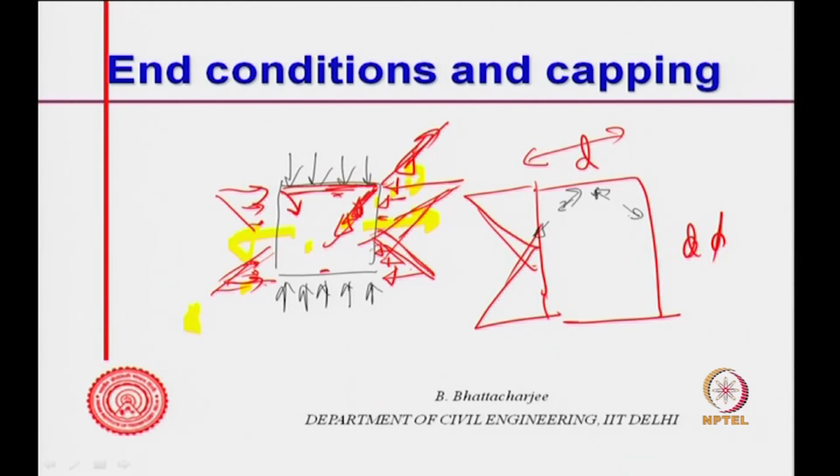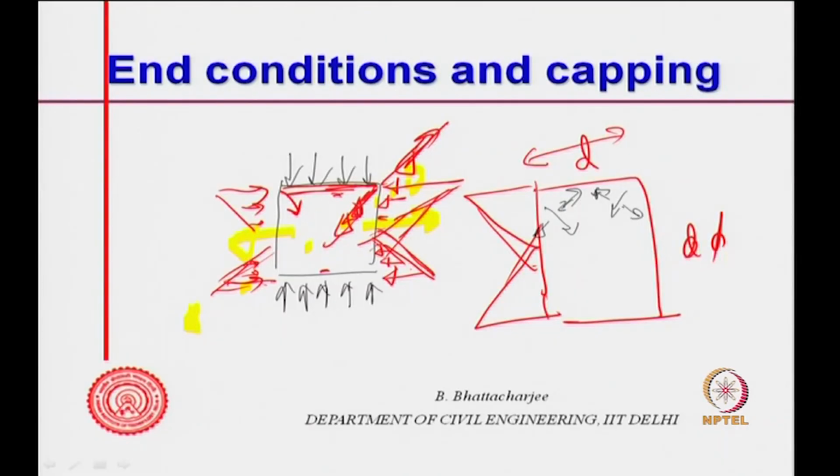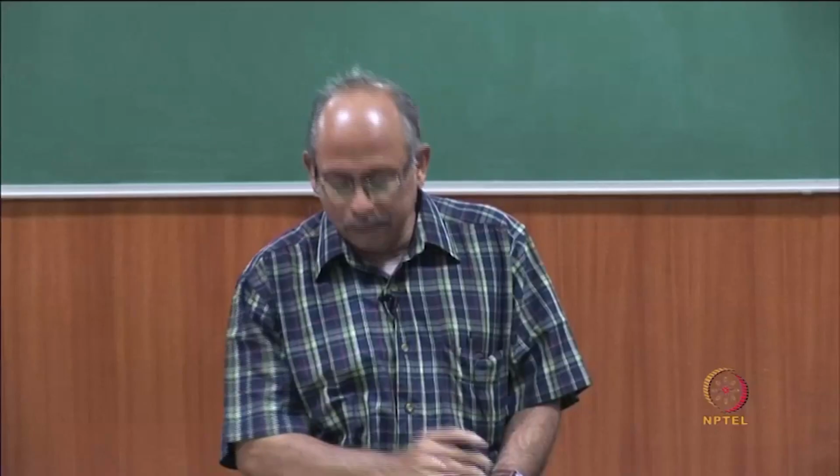So, tension acts like this because compression is along this direction, the net force being the resultant of the frictional resistance and the applied load. So, the net compressive force will be along this direction, which means the transverse tensile force because of Poisson's effect will act like this. So, you have a crack in this direction and in this direction. This is called the Platen effect.